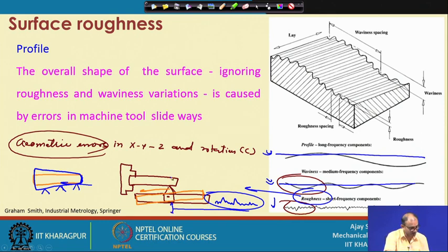If you see the optical materials, when the light passes through them, if it is a mirror then it will reflect, and if it is a lens then it will pass through it. So, if the roughness is as low as possible, then the homogeneity of the light which is passing through or reflected from the surface of the optical material will have the perfectly required dimension, but that will depend on this surface roughness. So, the smaller the roughness, the better the performance in many cases, but in many cases you always need a surface roughness also. So, that is a different case.